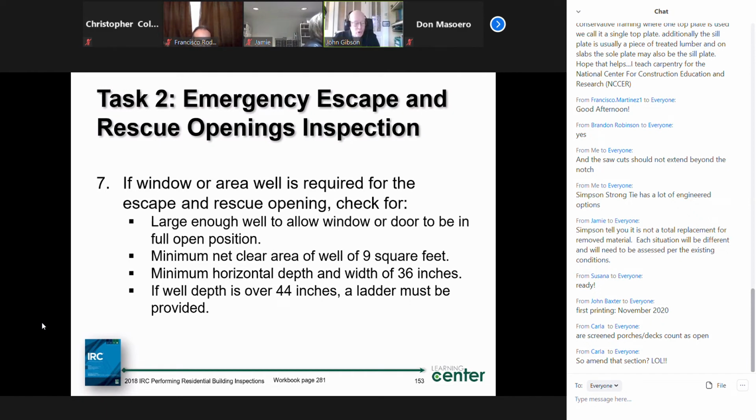The 2021 code said, well, fine, what do you require in terms of ladder? So the ladder, when you look at the spacing off the wall plus the foothold for the rung, they came up with, well, we need treads that are at least 5 inches. And then it said, what about risers? Well, rung to rung, we end up with 18 inches maximum. So therefore, the riser could be 18 inches. Now, you may end up doing a crawling type climbing mechanism, and it's just kind of pitched to get up those stairs. But that's how the 2021 code addressed this issue.